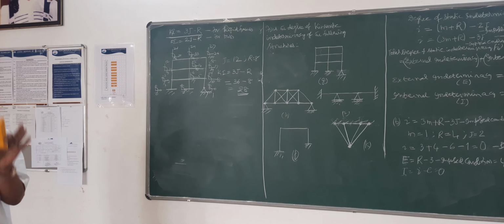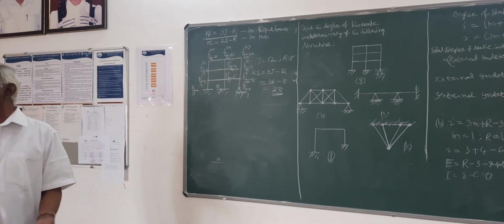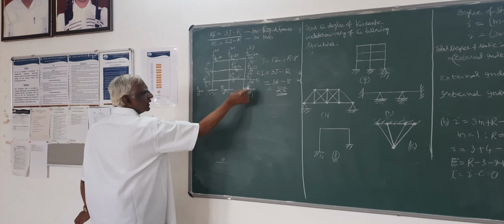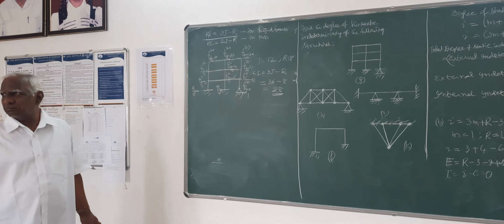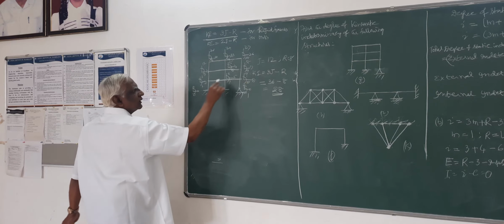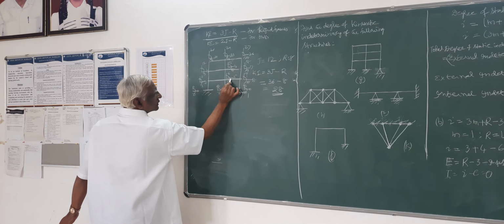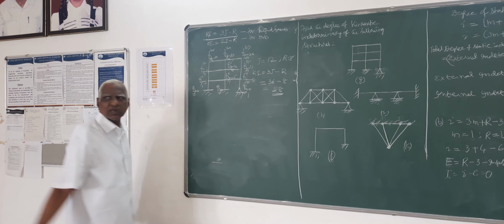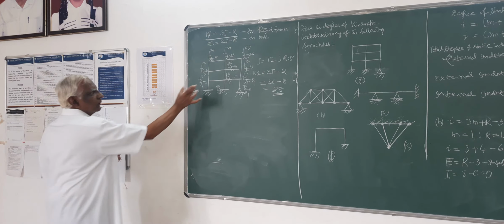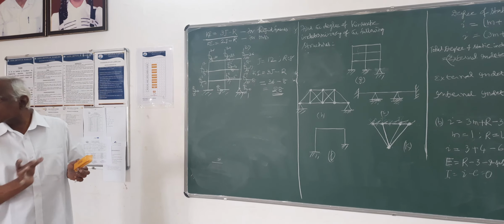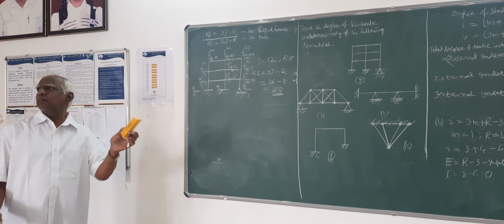Now, suppose the case comes where it is axially rigid. Here, no problem, it remains the same. Axially rigid means whatever this end moves, this also moves the same amount, and that also the same amount. Both these elements have to move as a rigid body by the same amounts.